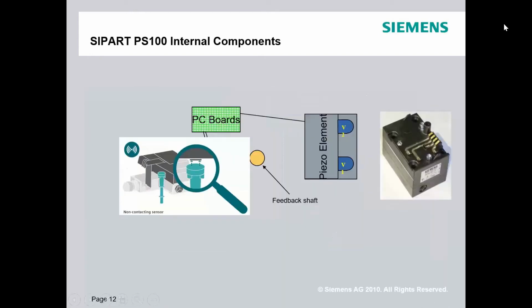All right. Let's talk about the PS100. The Siemens PS100 is our newer product. As Matt was saying, it is piezoelectric based. There are no springs, cams, things like that. The problem with the old cam stuff was that most of them came with 3 cams. You had a linear cam, a quick opening cam, and an equal percentage cam, and that's what you got stuck with.